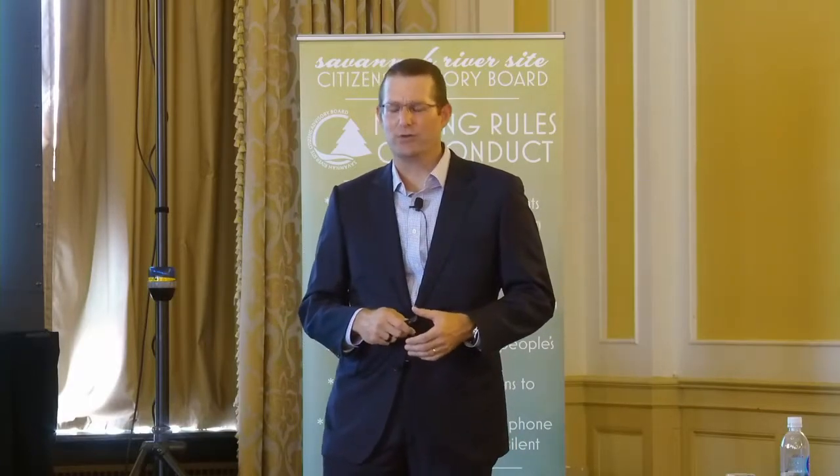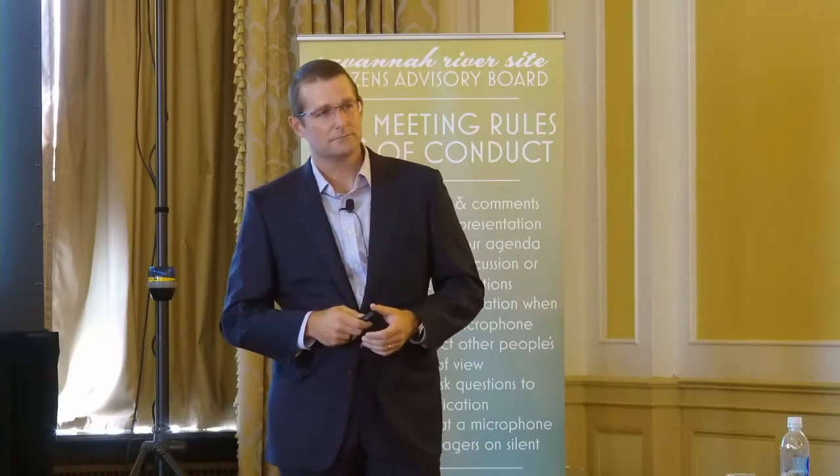We would probably at that point be looking into a pretty wholesale redesign of the equipment itself. Okay, and then the other thing is some sort of a premix of the liquid and the dry in some sort of a static mixer or something that would possibly start the wetting out of the cake a little bit beforehand, so you wouldn't necessarily have as much dry solids contact.